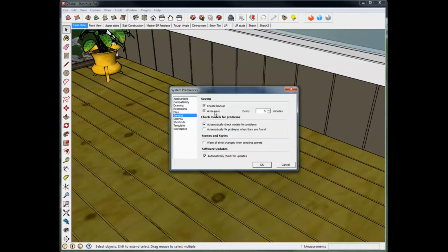The nice thing is, if you find that you've screwed something up, and I've done this often, the problem with 3D modeling is I can select something, say right here on this trim on this exterior window, and at the same time, if I drew a box around it, I could be selecting something that's down in the basement and not realize it. It could be behind it, and I could catch that, and then I delete it, and later I come into the drawing and I go down to the basement to look at something, and I've got stuff missing. I've had that happen more times than I care to admit.